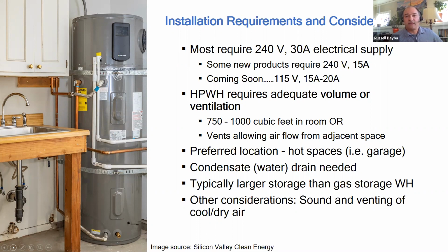Okay, so what is expected here of the install? Most are 240 volt, 30 amp power supplies, although some are 240 volt and 15 amp, which could be really helpful with panel size being an issue. And coming soon, there's going to be 120 volt, 15 or 20 amp service. And that is going to make a big difference when you're starting to add more electric appliances to have some of that flexibility.